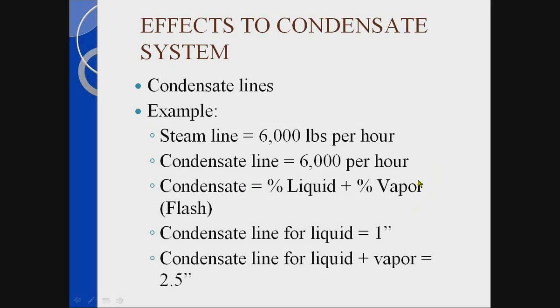And one of the biggest issues that we see week after week at facilities is condensate lines are not properly sized. And that's a big, big factor. But therefore, remember, condensate lines are two-phase flow. Size them for liquid and flash steam.